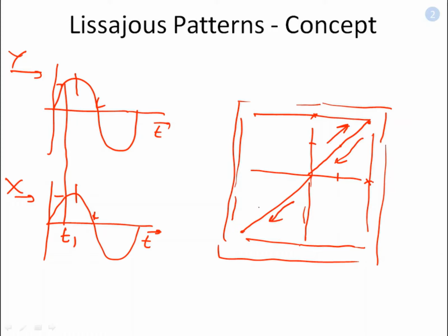So you can see this is a straight line at 45 degrees, for the case when both the signals are same across X plate and Y plate. So for same signal or for signals with same amplitude, with same phase and same frequency, you are seeing the straight line at 45 degrees.